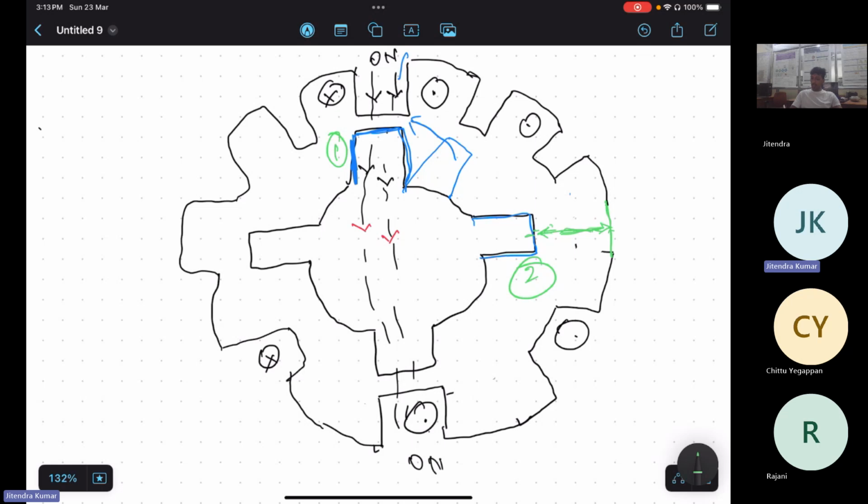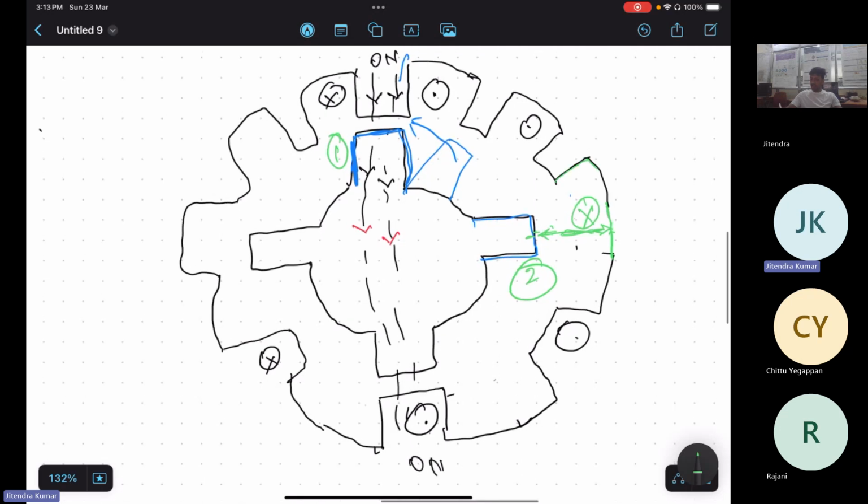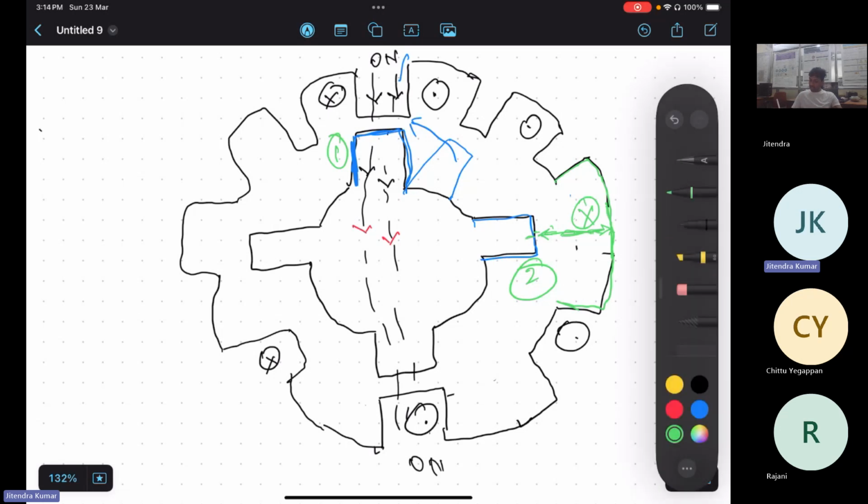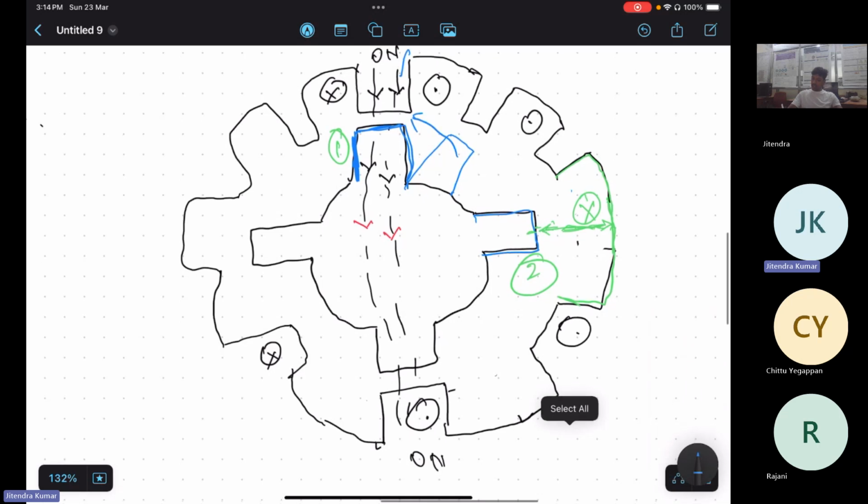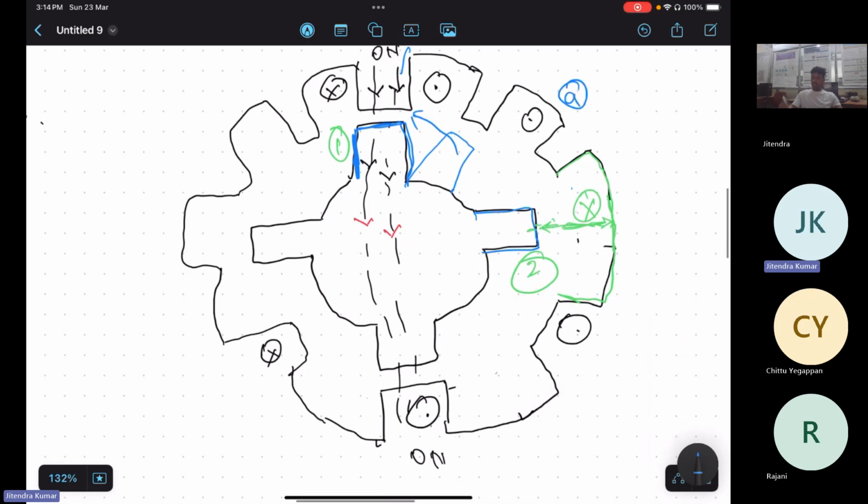There is less iron path, or the air gap is higher, because here let us suppose a coil is placed. So the effective air gap is higher. I hope you are able to visualize this as a slot, right? Yes, sir. Now what is happening? This winding will be turned on. Which winding? This, let us call it A. A winding will be turned on.